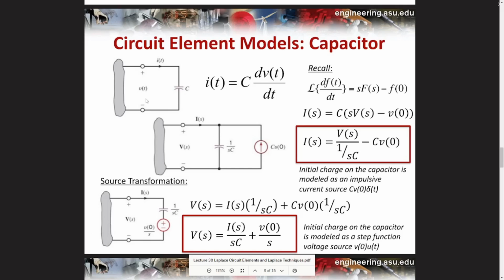What matters is that the initial voltage is positive on top here and negative on the bottom. So either we draw a current source or a voltage source, either way, that source is consistent with a voltage that is high above and low below. So the current source goes from low to high, and the voltage source has its plus minus matching. So this is the matching source configuration in source transformation.